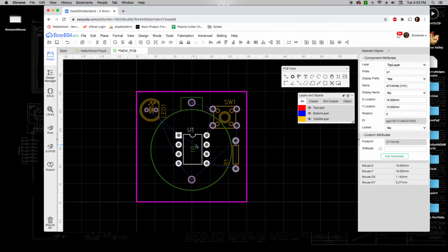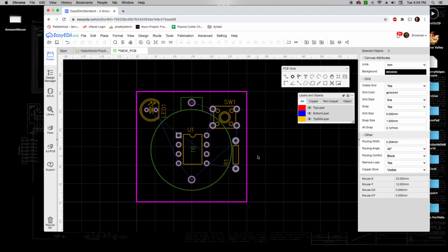And so you always think about your order of operations. We would actually solder all of these top components and then go solder on the battery. So as you're making things, just be aware about where you're placing your components, especially if they overlap across the top and bottom, and just think about how you would actually build this in real life. It's a really good exercise in being able to design things that are going to work.